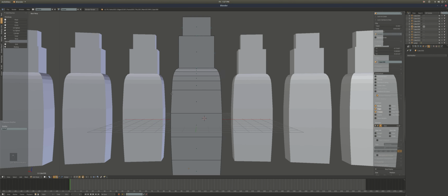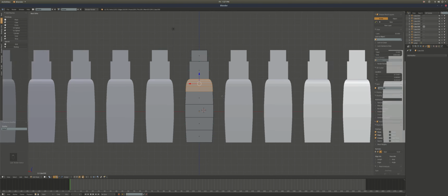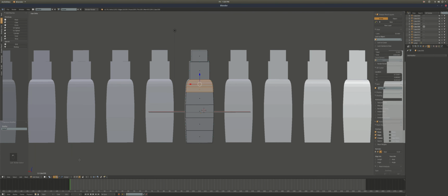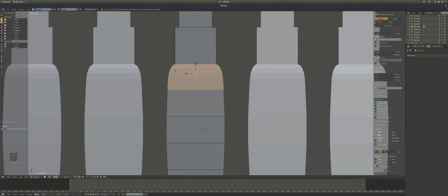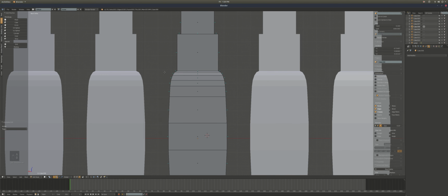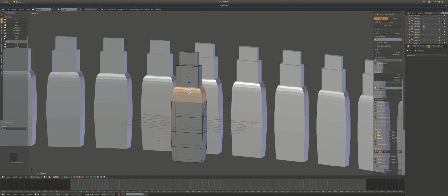If I wanted a perfect selection, you can go into perspective here, or drop out of perspective, and select these faces. You can also turn limit to selected off, and it's going to select like it would in wireframe, which is awesome. So it's going to select through the faces, and there you go, you got them all.